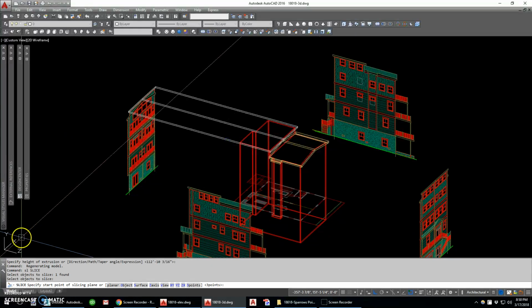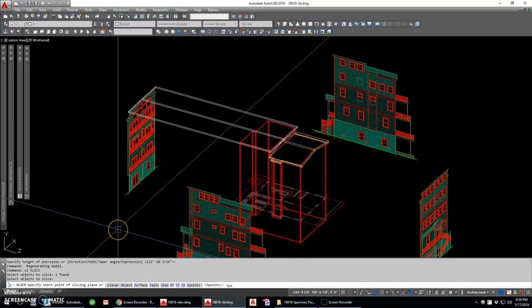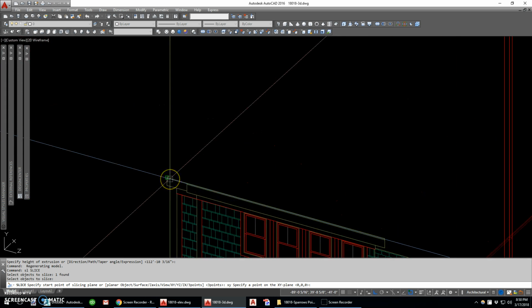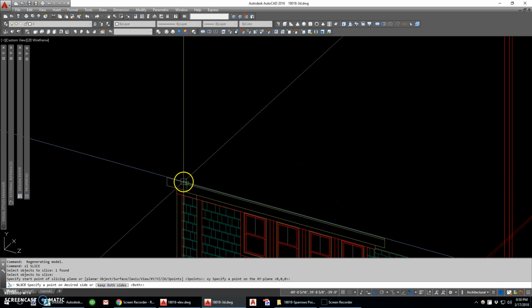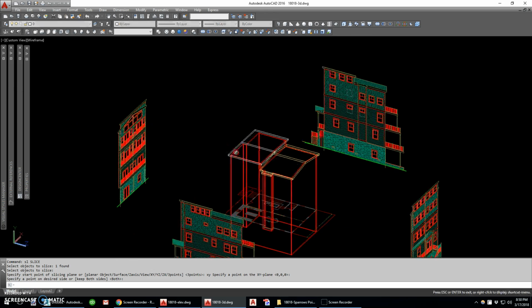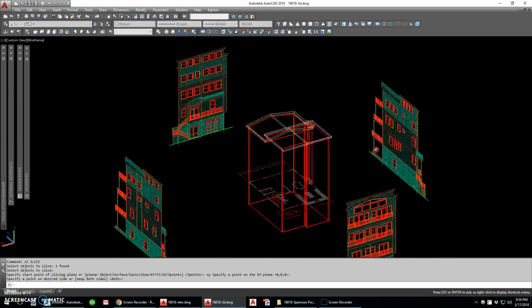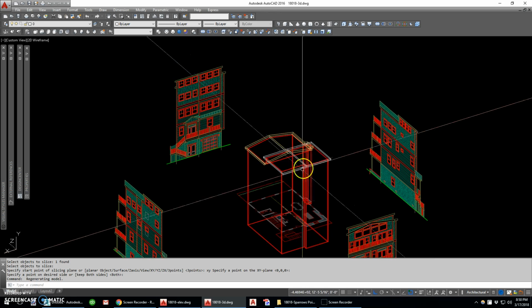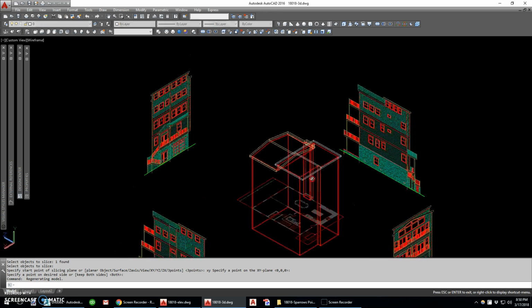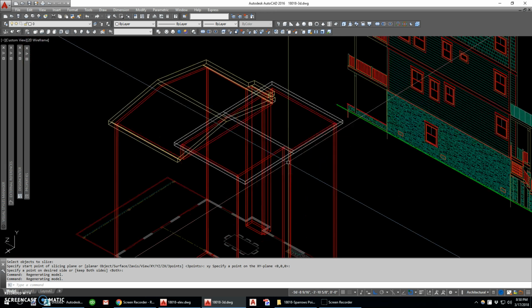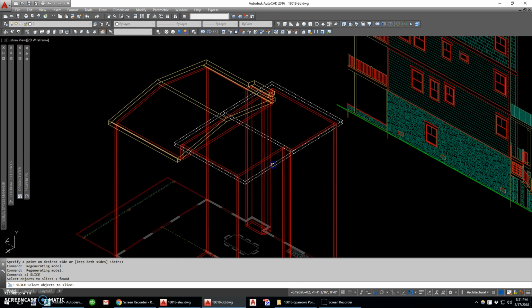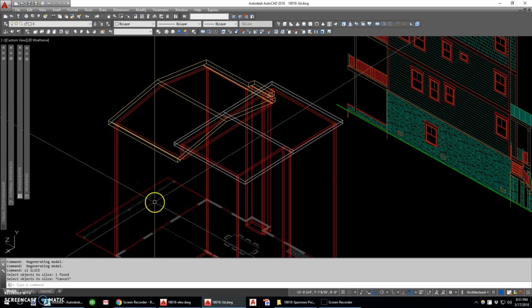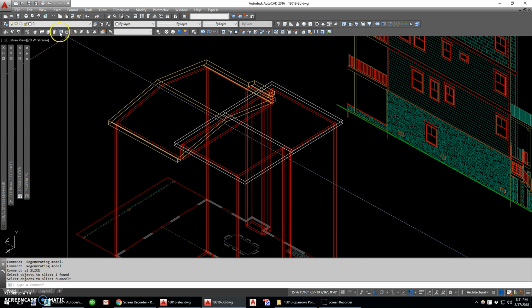So I'm going to slice it on my XY plane. Whoop, XY. And I'm going to use my furthest projection, and I'm going to keep this side. So now you can see the roof is about right, although it should set back a little there. So you could do this 10 different ways. What I'm going to do in this case is slice this object. And you can see my Z is going back. I'm still working on my back. I'd like to maybe change that to the front.